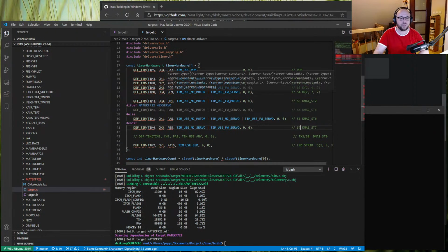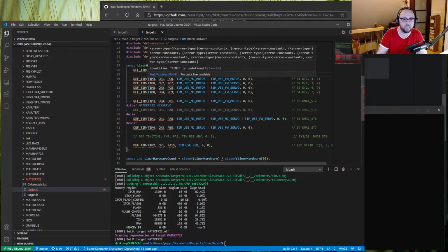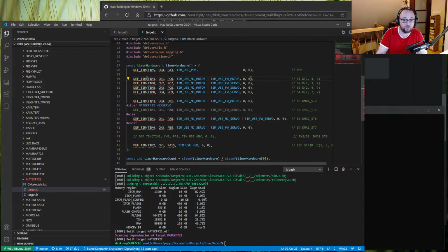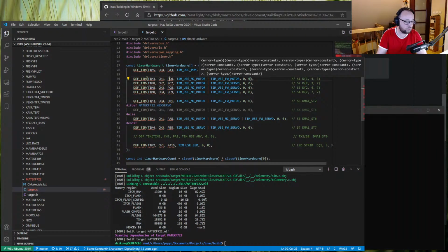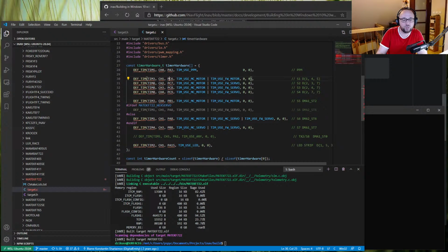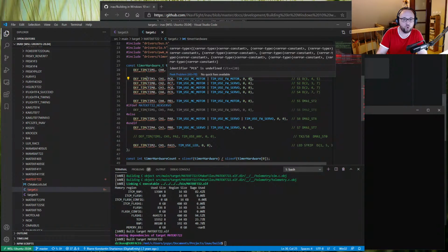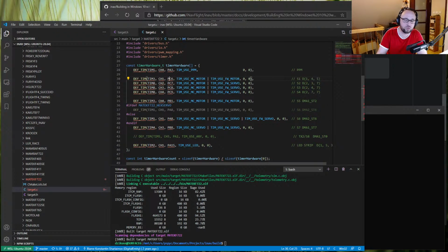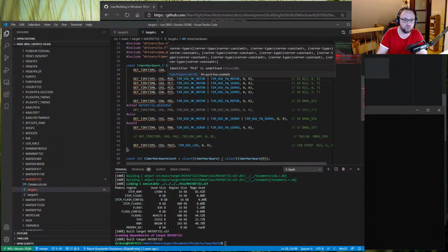What's really interesting in our syntax is column 1, column 2, column 3, and column 4. Column 5 and 6 are not that interesting. We will not be talking about them at all. What's really interesting in our case is, first of all, column C, the third column in this timer definition, actually def underscore timer. Column 3, the third argument for the function, is the information on which pin the output is assigned. In this case, output 1 is connected to port C number 6.